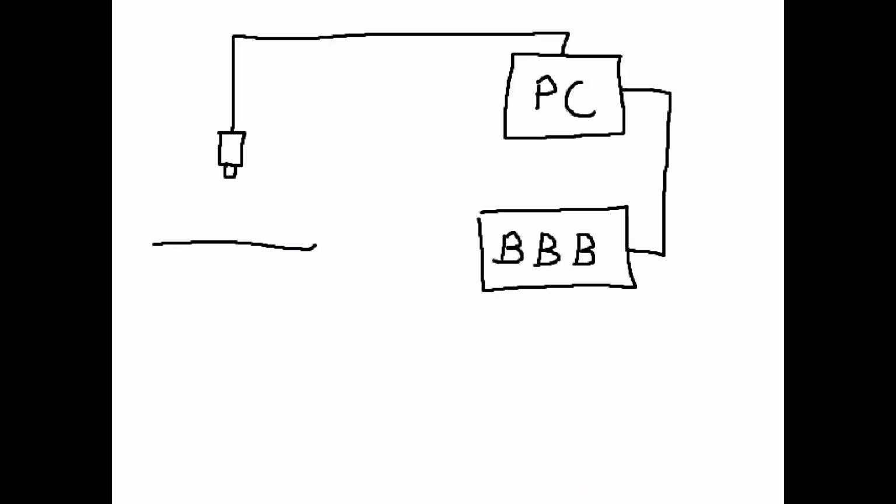So, to return from our digression, if an action module is controlling stepper motors, it just sets a frequency and direction in the PRU. A consistent waveform will be produced on a specific output pin until the PRU is told to stop. The BBB CSIO project handles all of the I/O interfacing with C# and also the interaction of C# with the code running in the PRUs.